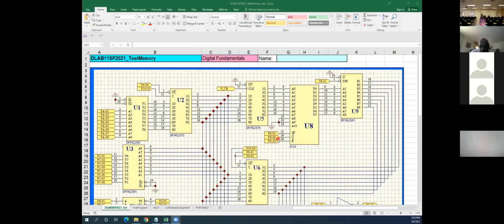Okay, you want to write data to the memory. Pin 21 must be 0. Pin 20 has to be 1. And pin number 18, it will be high, then low, then high, negative then positive. So the data will be ready inside that location. That's for write.